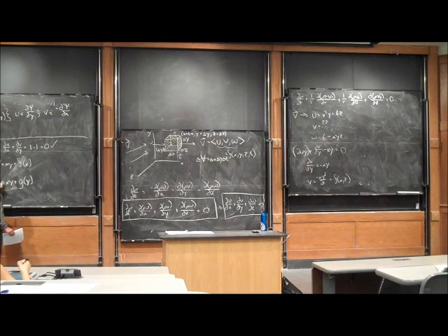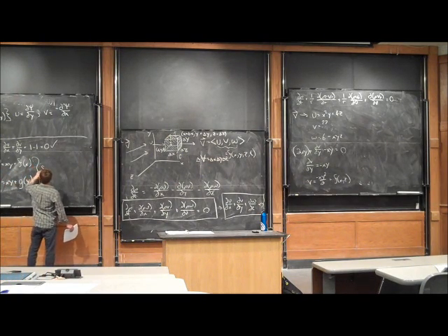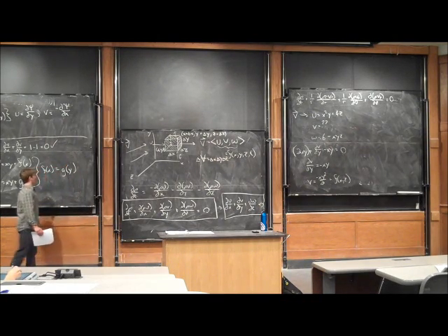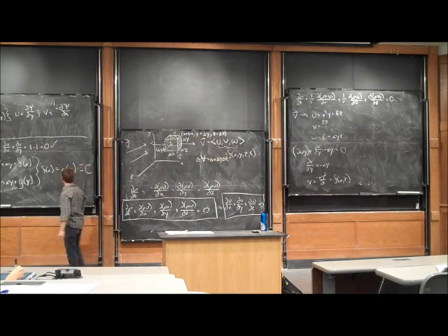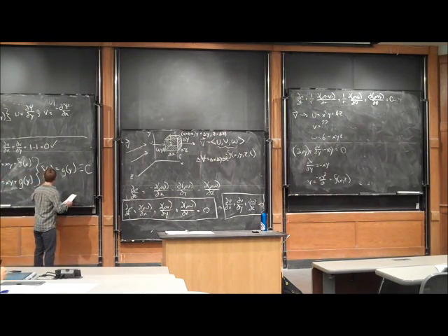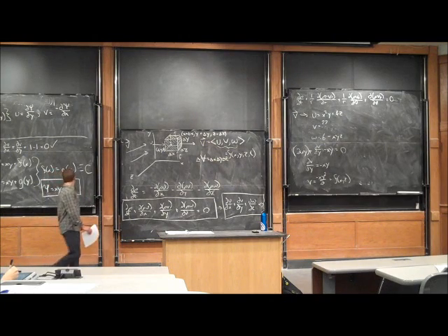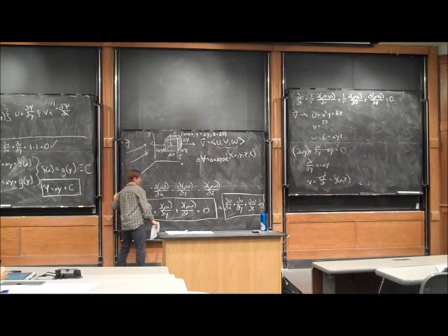Now, from differential equations, I know that these are both the same equation, so if I equate them to each other, I see that f of x has to be equal to g of y, and this is only possible when they both equal a constant. So now we know that psi is equal to xy plus a constant. And any constant is still going to be a valid stream function for this velocity field.